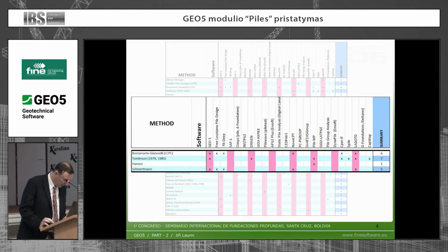So here, if you have a CPT, it's very well. At first, Eurocode 1992 is the same method, in fact, as the Dutch NEN method that computes bearing capacity of piles from SPT tests. The second one used is LCPC or the Bustamante method, which is again from CPT tests.